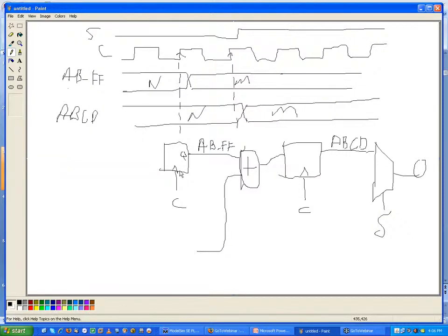So then you have not only the delay from clock to Q, but you've also got the delay of the wires, and you've got the delay of the actual logic, whatever it happens to be here. And then you may have some more wire delay, and then you actually have what's called a setup time, and that is the data has to be valid here on this D input a given amount of time before the clock goes high.